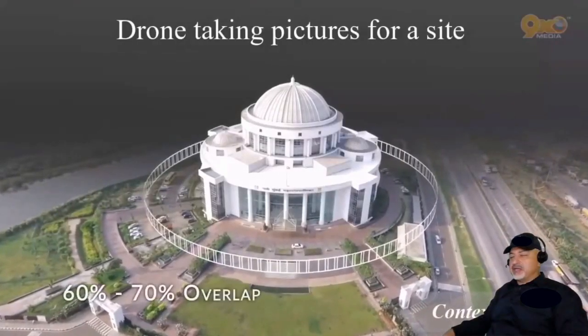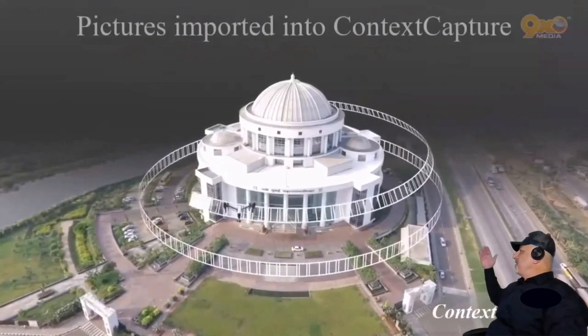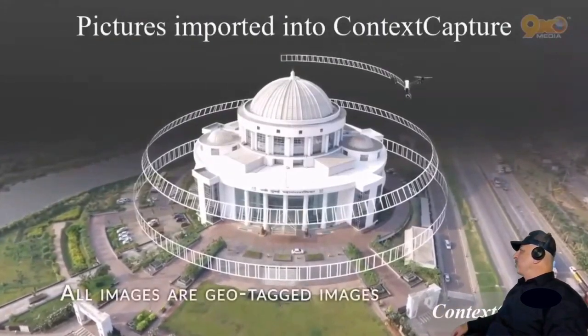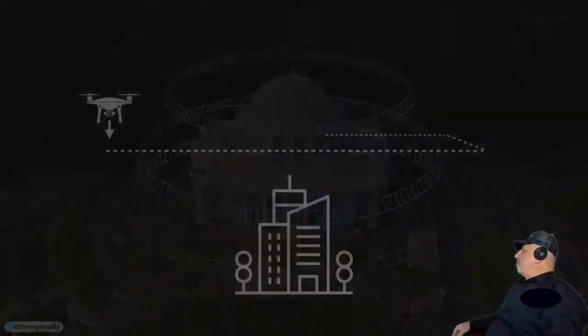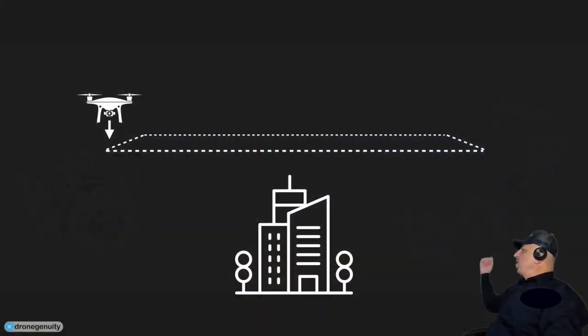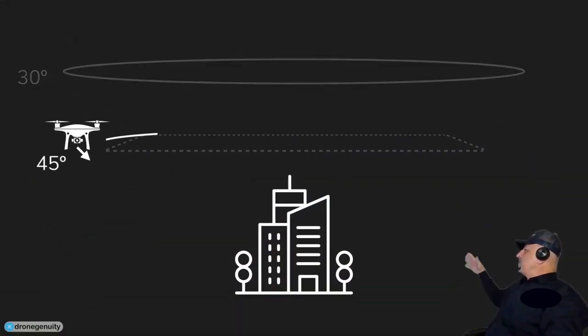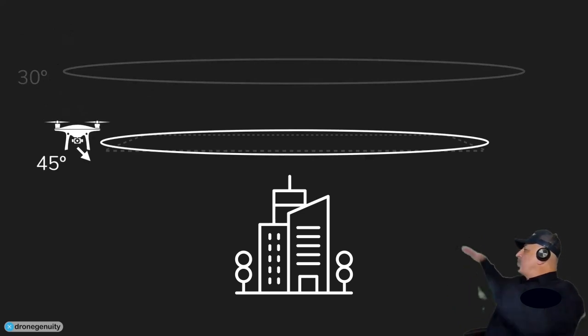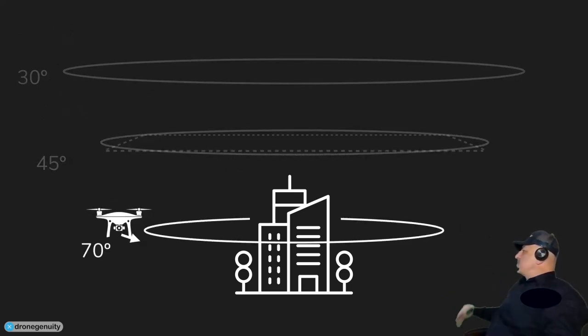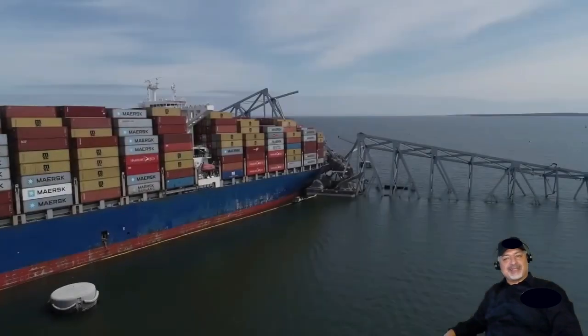How I wish the initial drone survey had embraced the full potential of photogrammetry, capturing the scene with the orbital trajectory and overlapping oblique shots at varying altitude, topped with a series of nadir images for comprehensive coverage. Instead, we work with traditional drone footage.